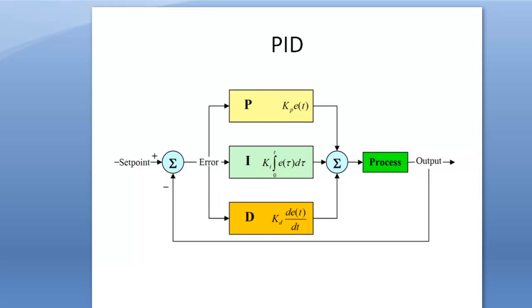Okay, so the PID controller, we already know the linear terms. Kp into e of t is the proportional term, then the integral term and derivative term. When converted into the Laplace transform or S domain, it becomes Kp plus Ki by S plus Kd into S. So this S term here is an integer power, that means S power 1, no fractional values.